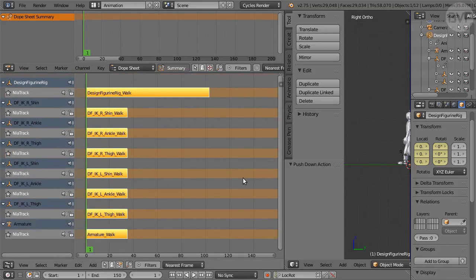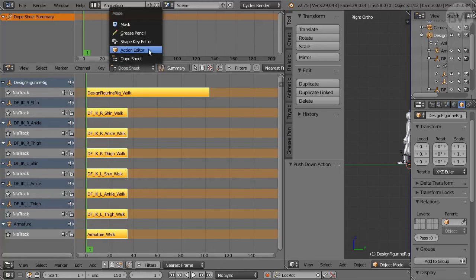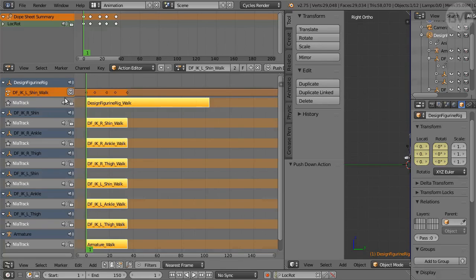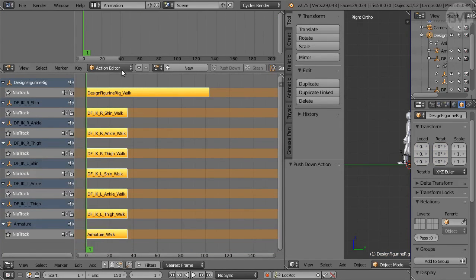As we pushed the actions onto the tracks, they disappeared from the Dopesheet. But you can check in the Action Editor view, they are still in the Action menu and can be edited. However, if you're not completely sure what you're doing, the Action view can be dangerous. It's easy to make mistakes editing actions on NLA tracks where they don't belong. So remove the action from display if you've selected one and return to Dopesheet view.